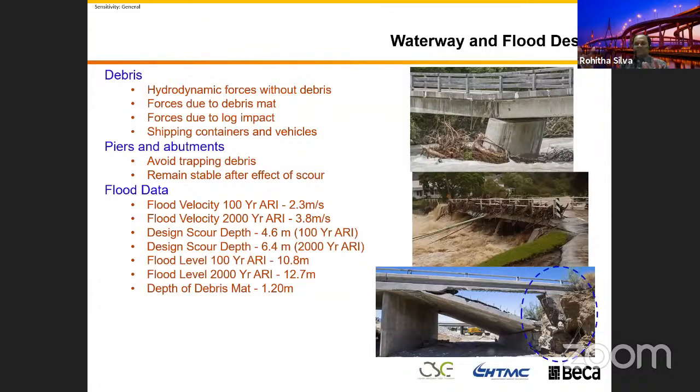That is the perception of the public, and it's the same around the world. So the argument here is people say you can't access the bridge, so why should I design for it? That is not right, because your access road you can reinstate within a week or two, or less than a month. But if your bridge washed away, you have to remove the bridge and rebuild it. It's a significant cost and time. You have to close that whole highway for that period of time.